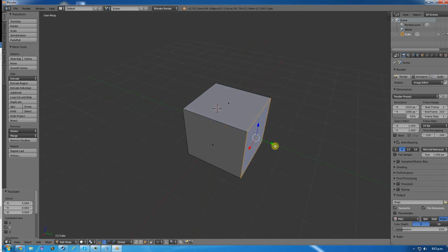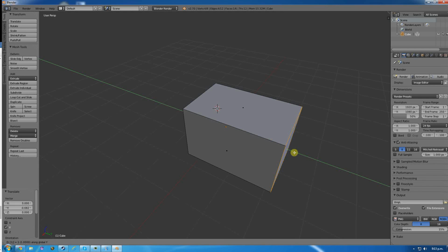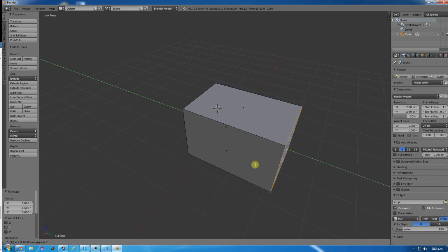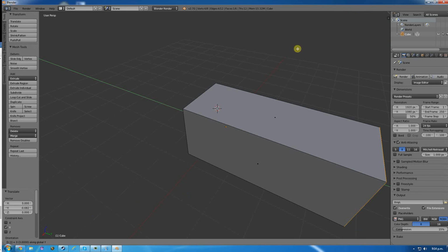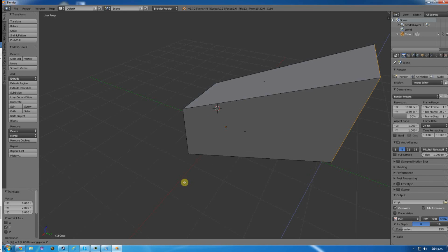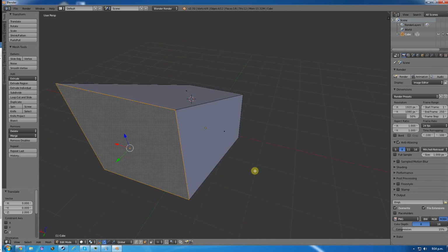When you're grabbing and then move it along that Y axis, I can also move it a certain amount. I can move it 1 unit, 2 units, etc. In this case, I've got 121 units. So if I move 2 units, it's there, 3. You can see down the bottom left, where my mouse is, I can type something in, so 2, and that'll move 2 along the Y axis. Hit enter to lock that in. If I then want to grab it and move it along the Z axis, 2, I can hit enter and move that 2 along the Z axis.